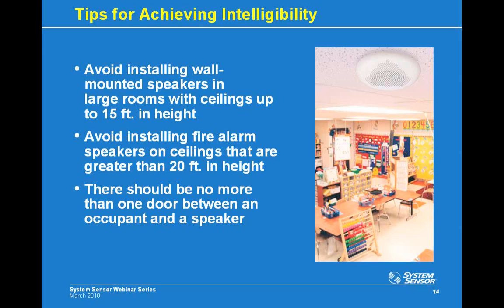And also areas with both high ceilings and highly reflective wall surfaces, such as marble, will cause additional challenges with intelligibility. And finally, there should not be more than one door between a speaker and an occupant who will need to understand a particular message because, on average, a closed door will cause a loss of 25 dB.